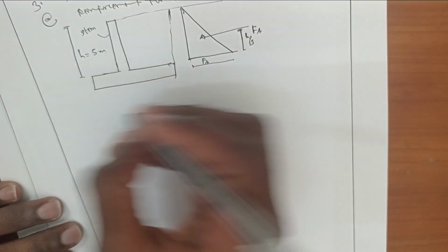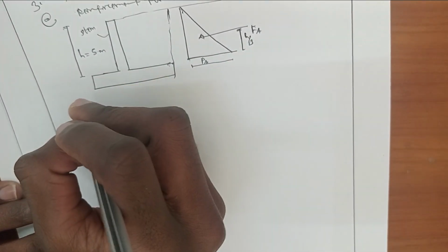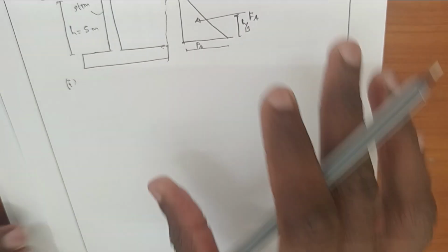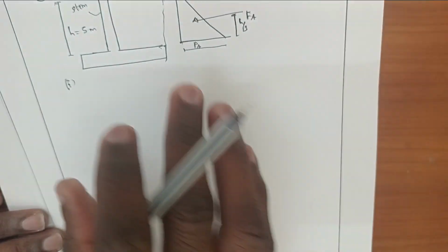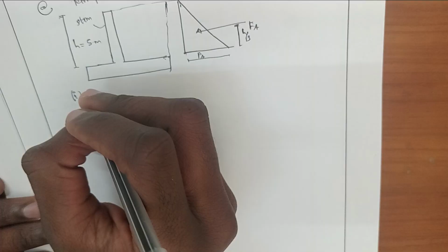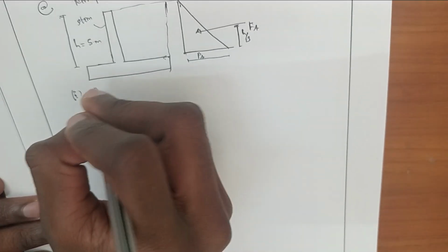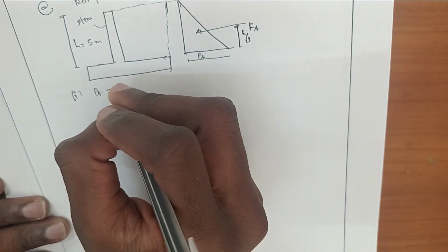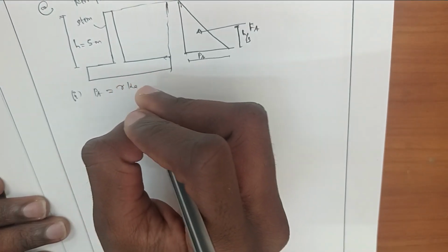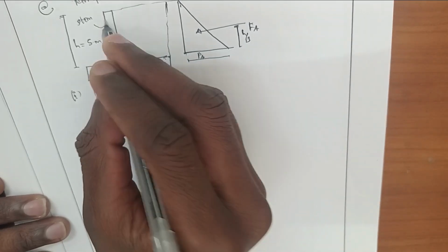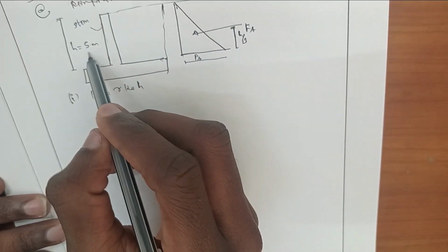Now let's determine the first step. During the design of reinforcement of the stem wall, the first step, let's determine the soil pressure as active pressure. Active pressure is obtained by taking unit weight times coefficient of active pressure times height of the stem. This which are 5 meters.